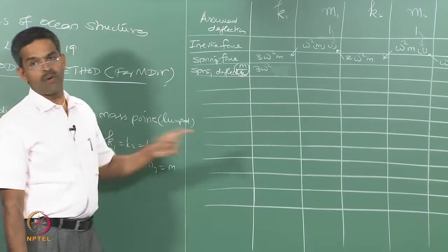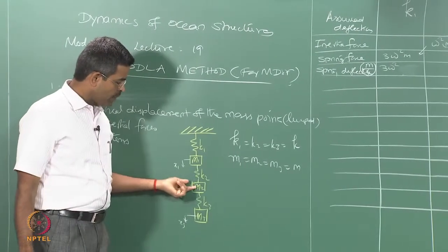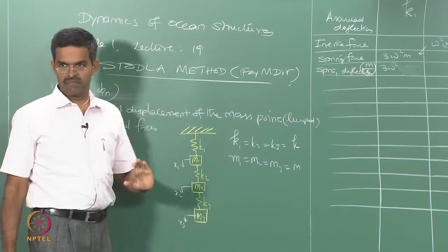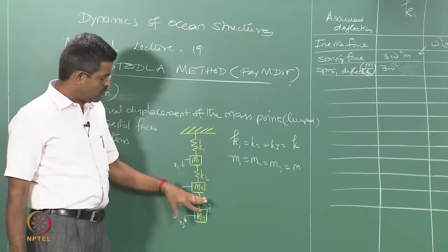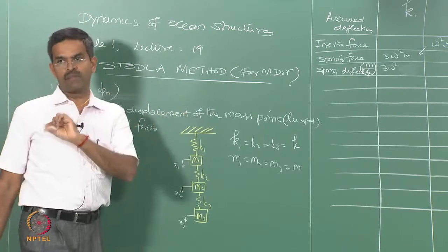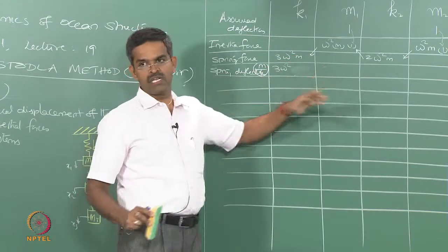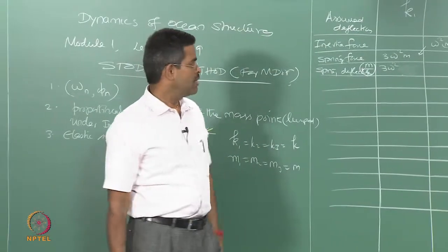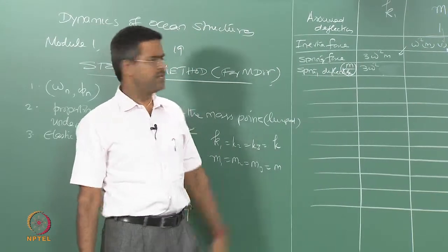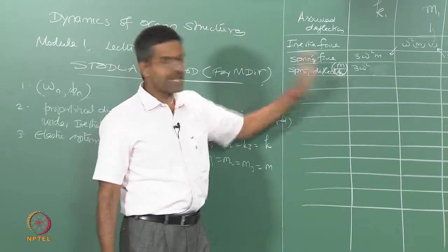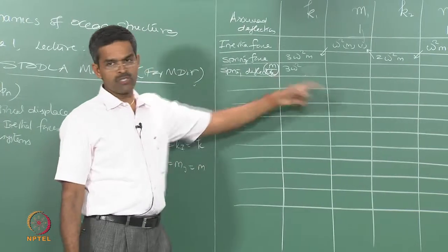On the other hand, it is very important for us to establish the proportional mass of m2 and m3 in terms of m1 all the time. Similarly, the proportional ratio of K2 and K3 in terms of K1. It means I have a common multiplier. This is only to facilitate the units of iteration. If you have a larger unit, iteration becomes difficult, because mass and K values will be very high in the real problem, 10 power 6. So we need not have a multiplier of this order here, we take it out, keep that value as a multiplier, we can use it later. So, get only the proportional values inside.